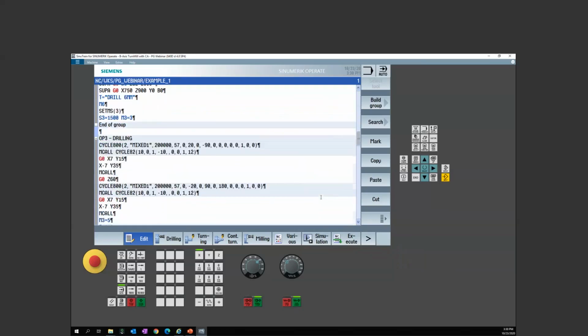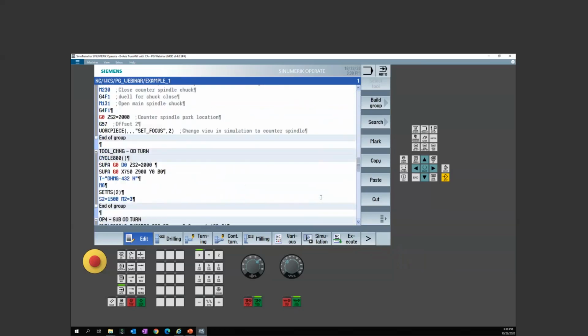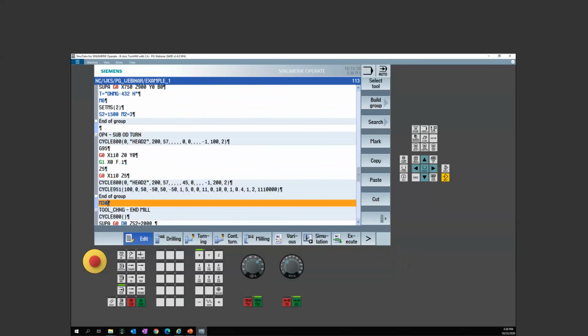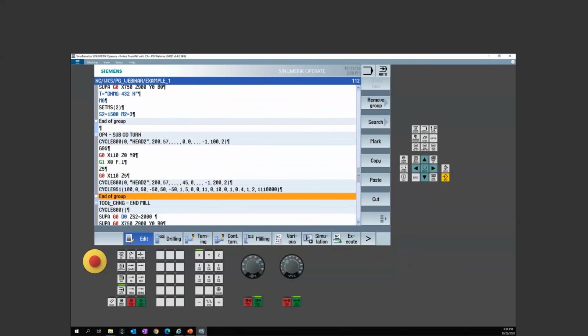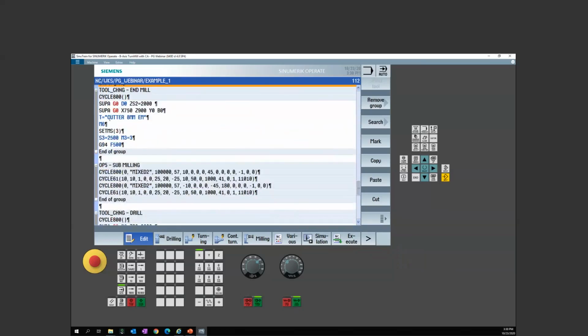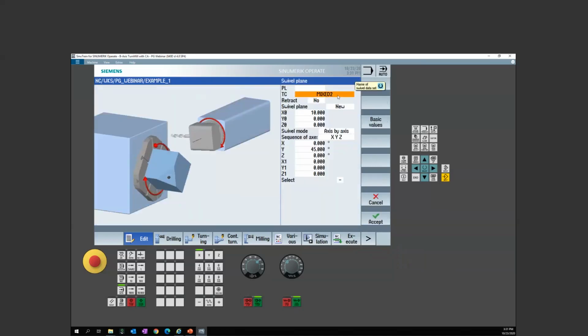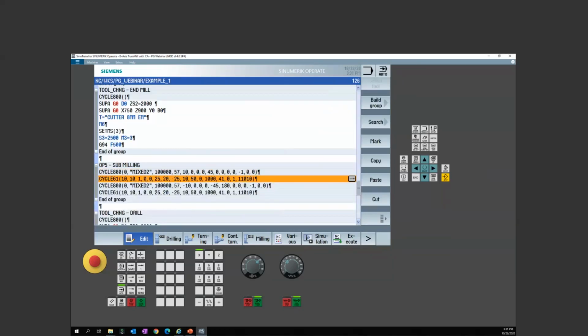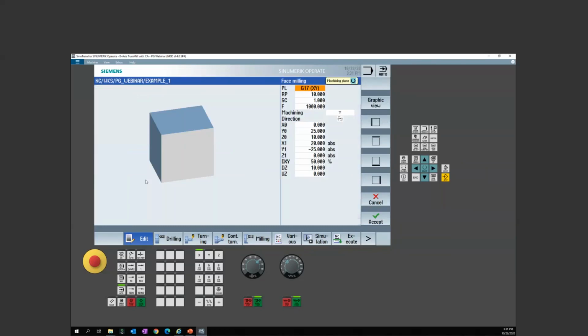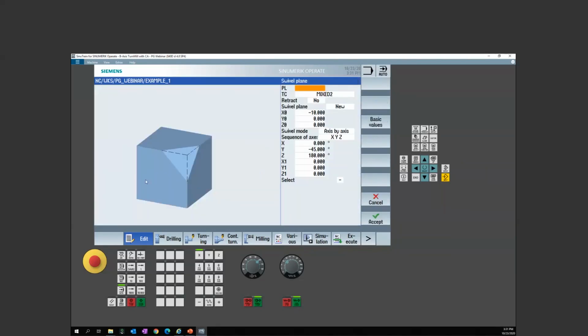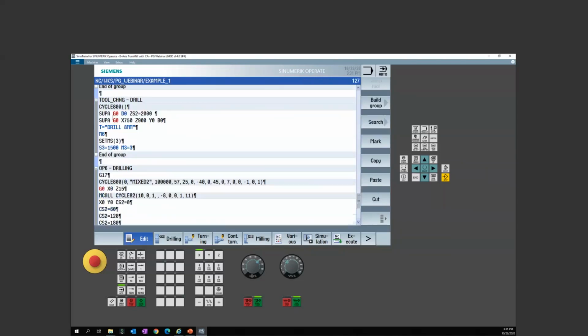But our final tool path here, there's our transfer. This was our turning. We're going to do the mill of the plane. Here you'll see I'm using mixed 2 because I'm in a swivel plane, but I'm working on the sub-spindle. And I'm just using some simple facing cycles to machine my 2 flats. There's my 180 degrees out. So this isn't the C, this is clocking the coordinate system, right? As I move around. And then we're going to load a drill.